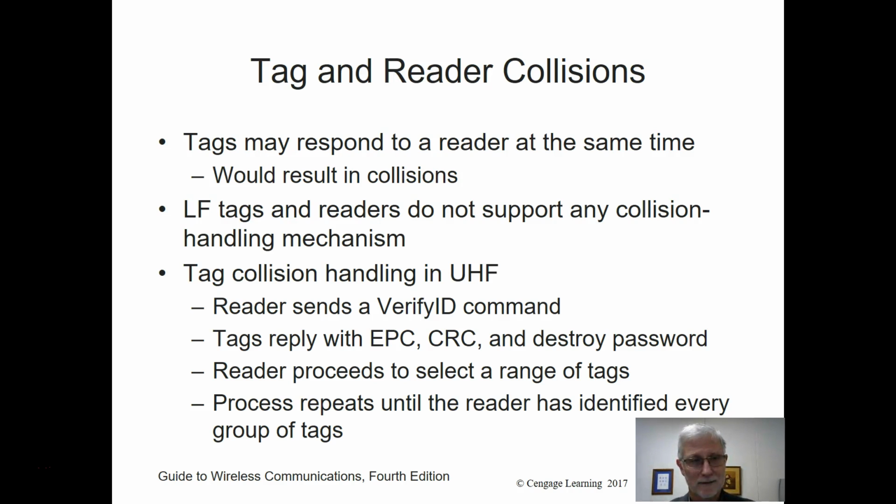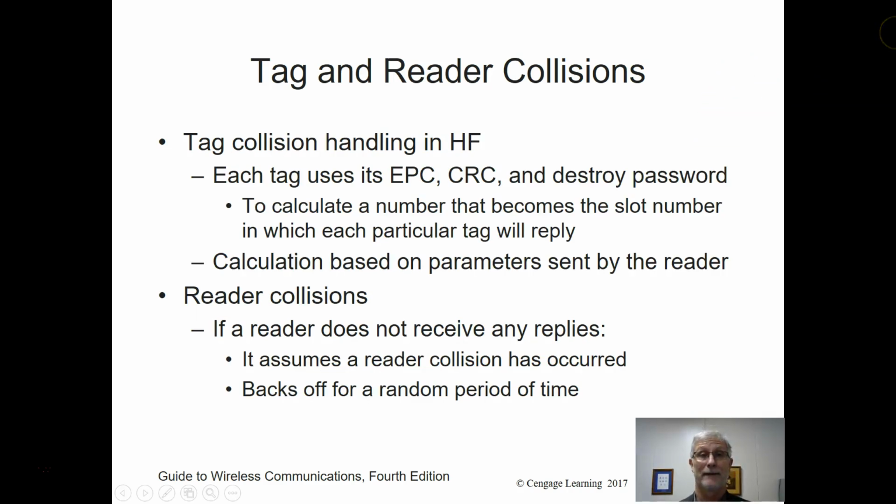Now, some tags and readers do not support collision handling, but the UHF says, hey, it sends out a verify ID command. The tags reply with its code, CRC, destroy password, and then it kind of proceeds to select whatever range of tags it wants and repeats to get everything. So it kind of goes through a process, verifies itself and then processes through it. Now, if there's a collision, I can calculate a number that becomes a slot number, which then can be reprocessed. So I can kind of back things off a little bit.